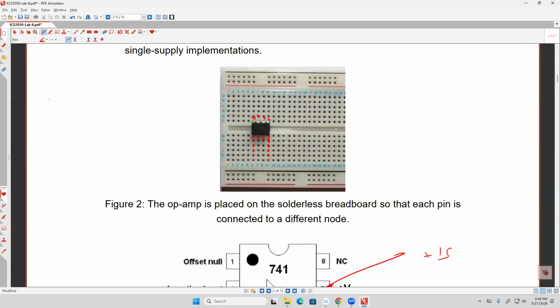There was a very small explosion and a crack. I actually damaged the chip. Okay. Why? Because the voltage was too high. That's why you have to be careful. Don't connect the power supply until you check the voltage first. Make sure it's right, because if you apply a very high voltage, you are going to damage it. You're going to crack it. Okay.